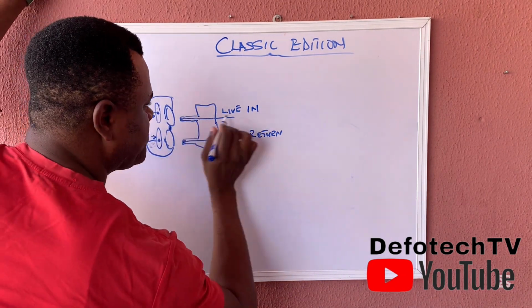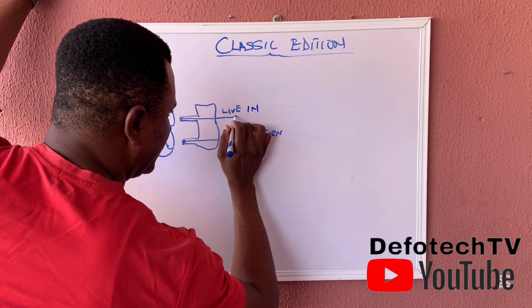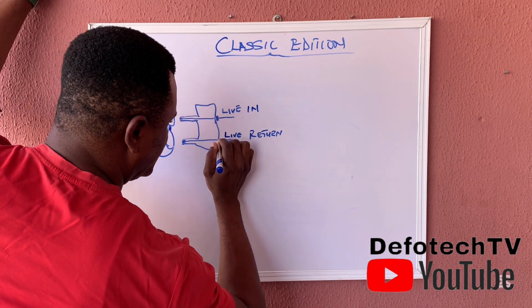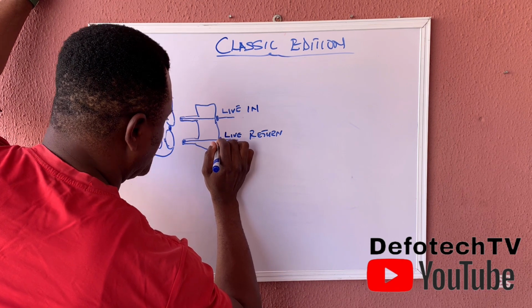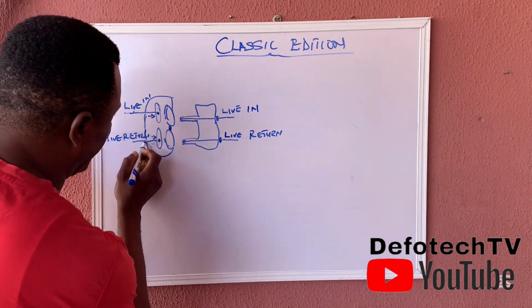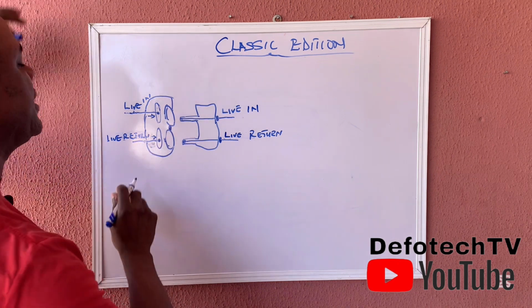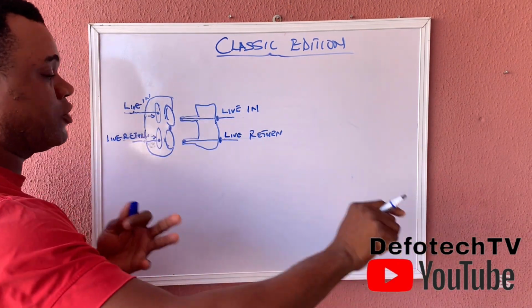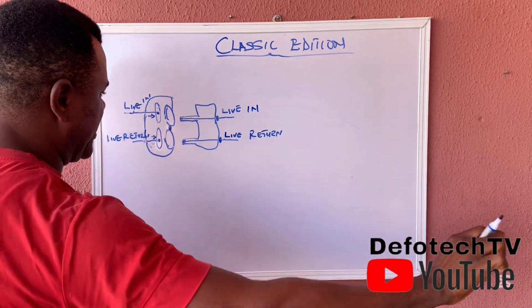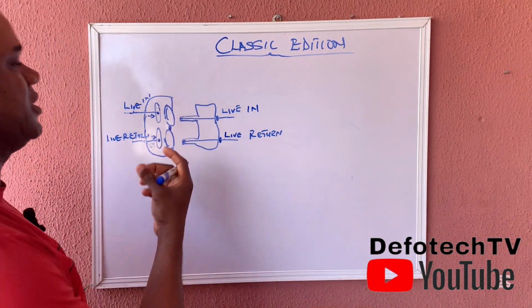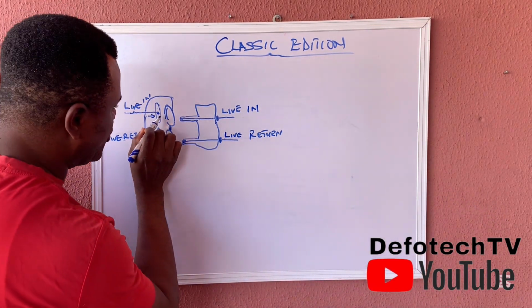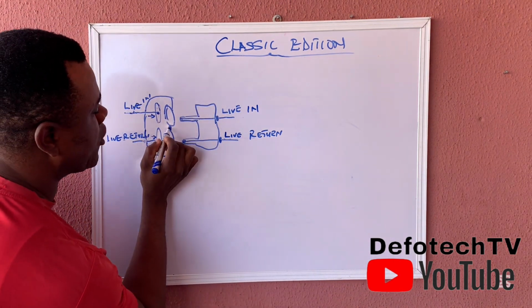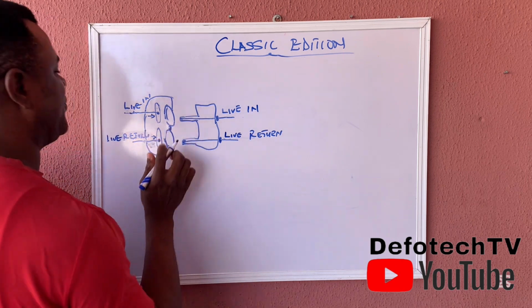This has the terminal here, and at the back of it you have your plate, where you have your terminal screw to hold this part. Then here you also have a terminal screw to hold this. But I want you to understand what we have inside. There's a spring. That's why when you push a gate contact, you're forcing a spring in. By the time you release, the spring returns, and this one comes in contact with this. This one comes in contact with this. Because there's a link here, it closes the fence.